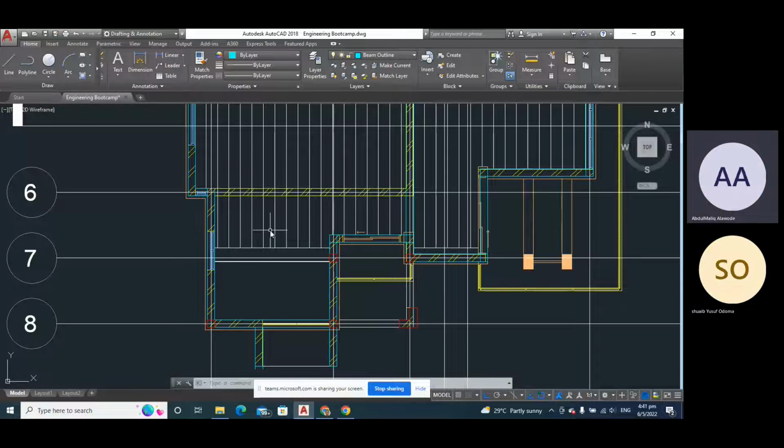Some people depend on block wall. Block wall is not dependable. They will tell you, okay, after doing my block wall, I'm still going to waterproof. Waterproofing has limits. Once the effectiveness of the waterproofing elapses, there is high tendency of the roof leaking. By the time the water here has exceeded a certain limit, the block gradually is going to be losing strength. That's why sometimes they waterproof the roof, but like 6 months later, everything has become messy.